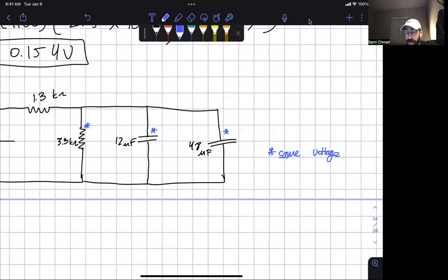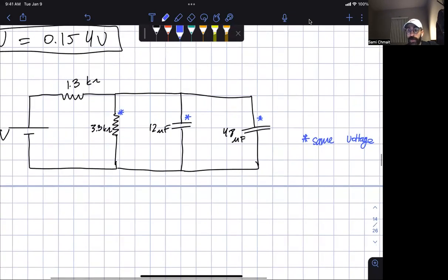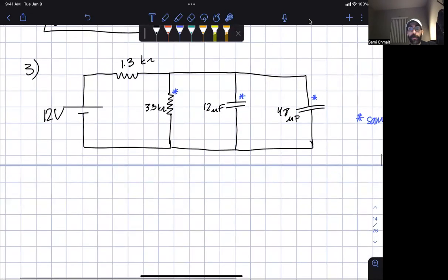So to be able to find what that voltage is, you need to first find the current. And the last thing I want to add is that a fully charged capacitor, when they say the system's been running for a long time, it's been connected to the battery for a long time, anything along those words, that tells you you're at steady state, meaning there's no current actually going through the side. They're fully charged, okay? So how do we work backwards for that voltage?